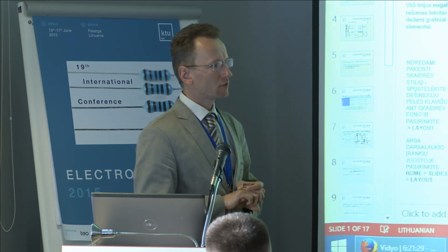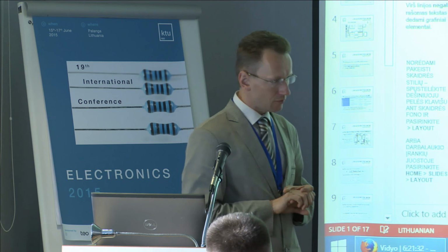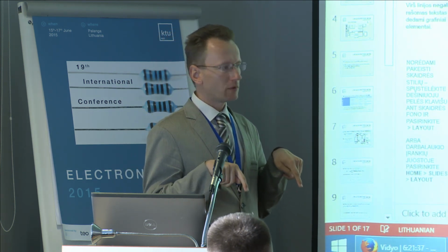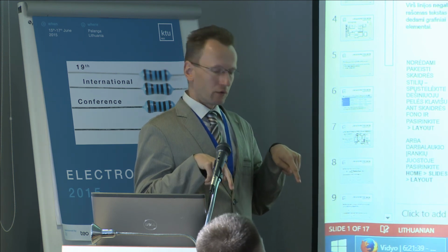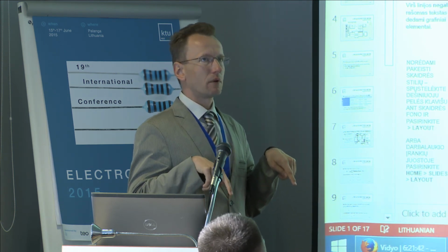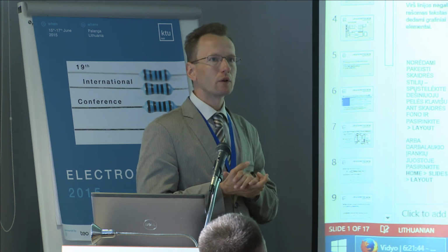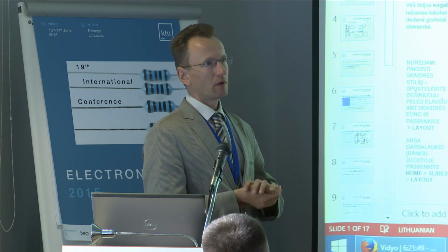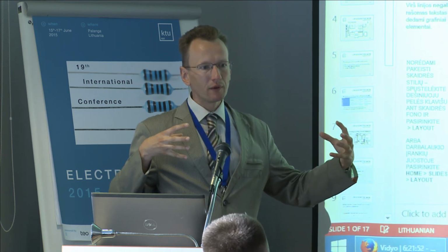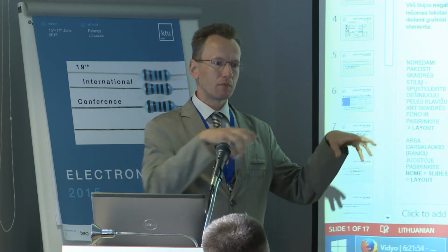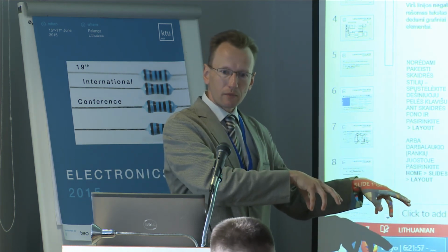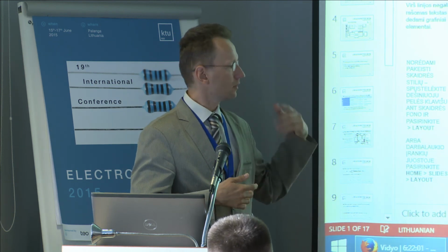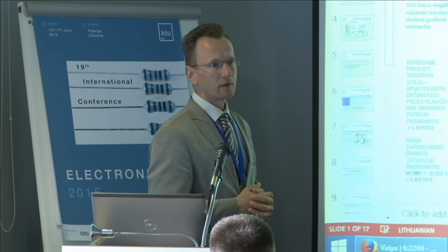About the noise level of the sensor, we actually measured that noise with an RMS meter on the real board, because it turned out quite a bit larger compared to what was given in the specification of the sensor. So basically we have a formula. We take some parameters measured from a real prototype, some come from documentation, and then we calculate this. Like limiting errors? Yes.